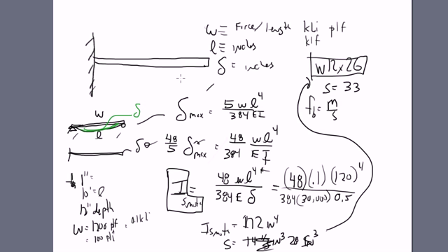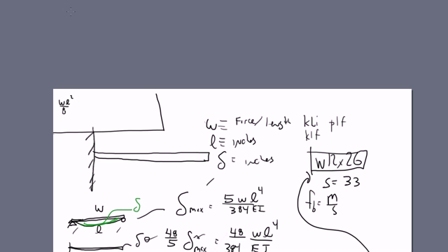Another multiplier type formula, and I'm going to take advantage of this extra space up here to remember that for a beam, the maximum moment simply supported uniformly loaded is WL squared over 8. But it was 4 times worse, or WL squared over 2, for a cantilever. You can go about that, doing that however well you choose. So it's going to be WL squared over 8 times 4.